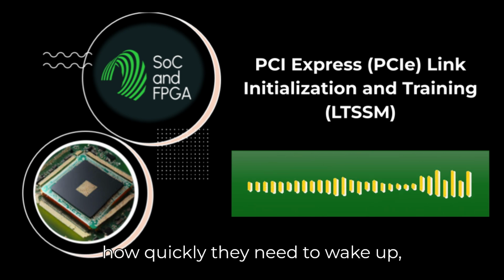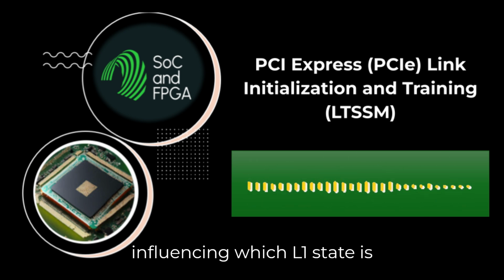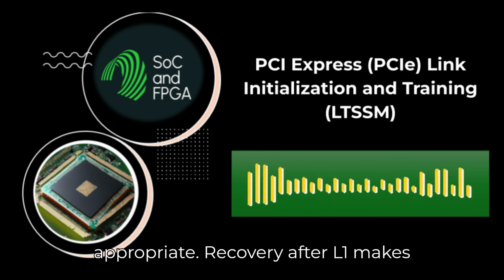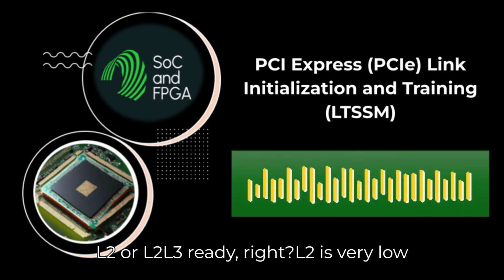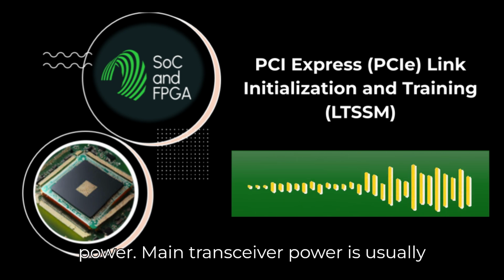Devices tell the system how quickly they need to wake up, influencing which L1 state is appropriate. Recovery after L1? Makes sense. Okay, now for the really deep sleep, L2 or L2, L3 ready. Right. L2 is very low power. Main transceiver power is usually off.